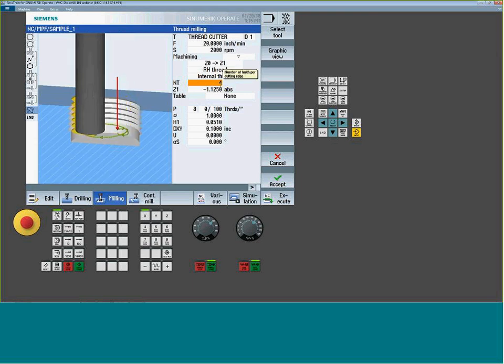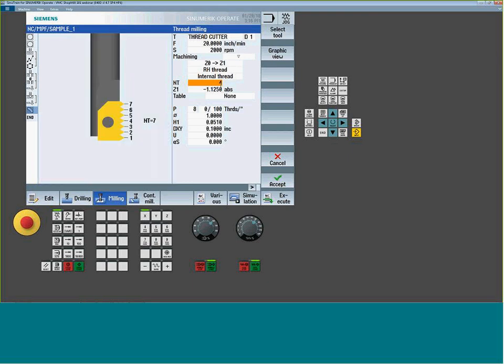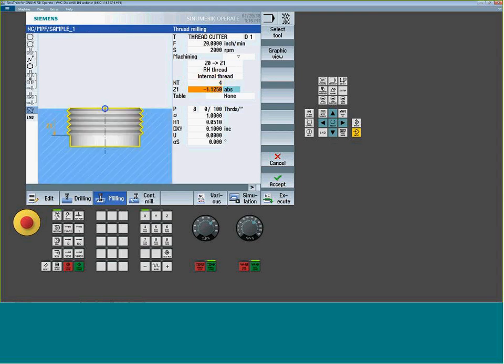Because if you tell it more, it's going to try to do that entire geometry, maybe only 1 or 2 revolutions. So, it's going to calculate based on the thread geometry I'm going to give down here, how much per the depth of the thread, that thread tool would accommodate.